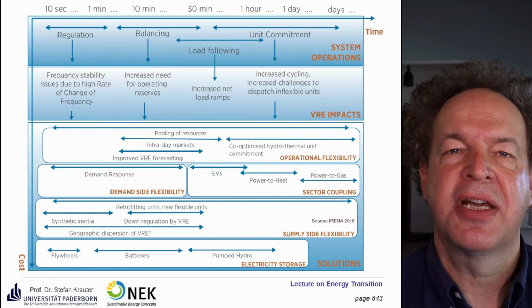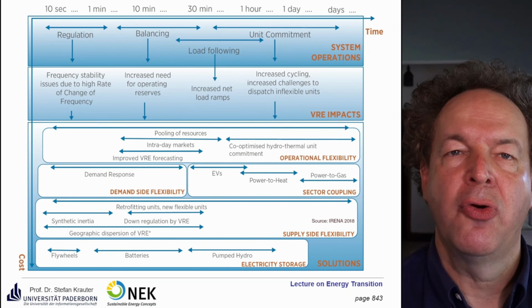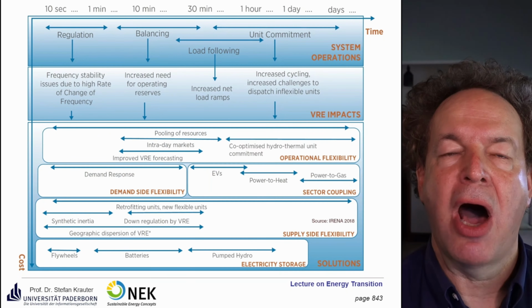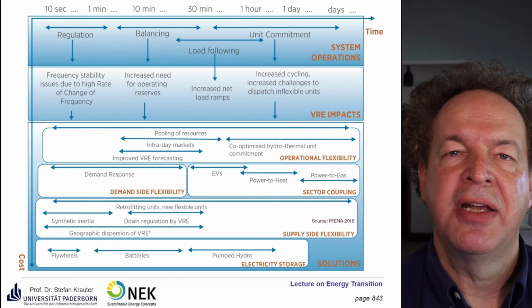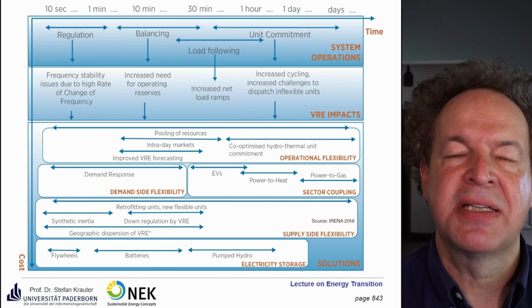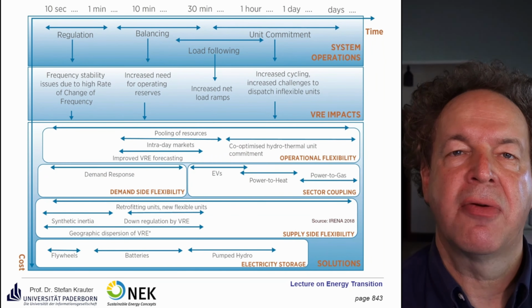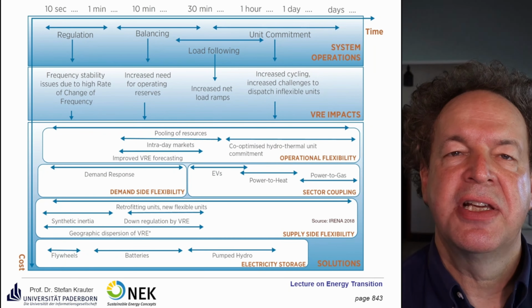This is not usually the case at variable renewable energies, maybe at hydropower, but for wind and solar, usually you are operating with variable speeds, and therefore the generation units of variable renewable energies, such as wind power, do not turn synchronously to the grid frequency.